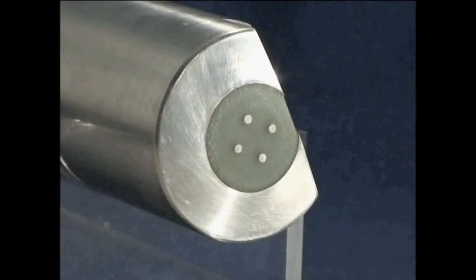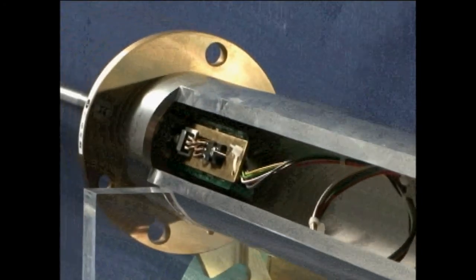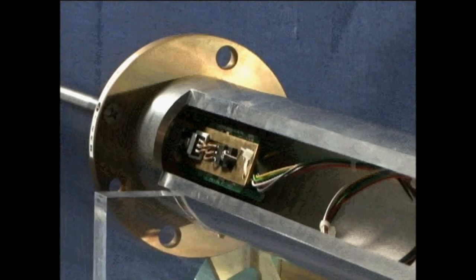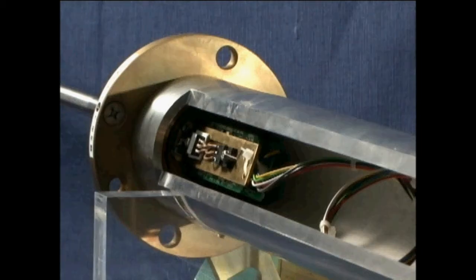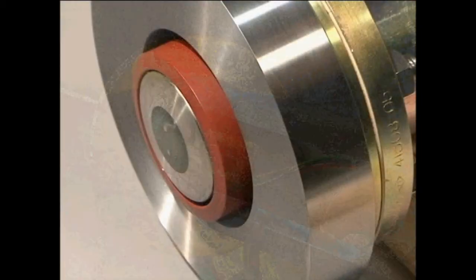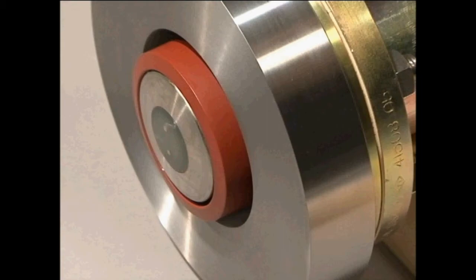Shown here is an example of an EM log with an orthogonal bidirectional sensor. It can measure movement speeds fore and aft, port and starboard. At the tip of the device is an electrode, inside of which are a coil and an amplifier that generate a magnetic field. The length of the sensor protruding from the hull bottom varies by model, but normally it's between 7 and 50 millimeters.